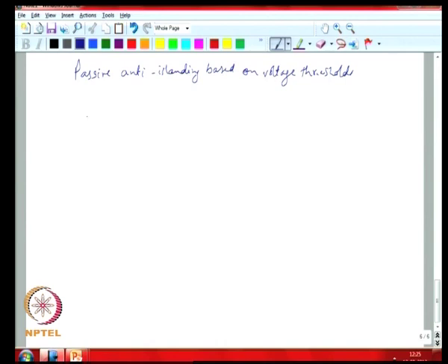So, the power injected by the DG is nominal, and if the actual load on the feeder is slightly different, so if the actual load R prime is R plus delta R, then you have now a delta P flowing into that network.